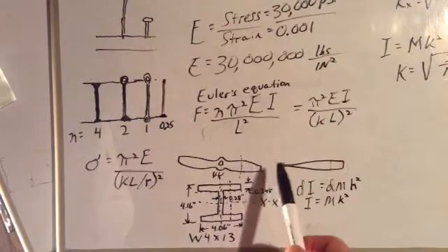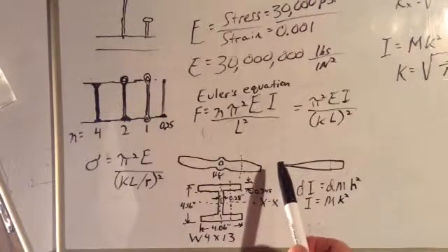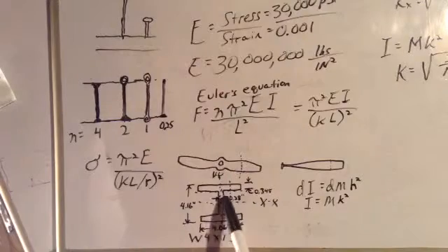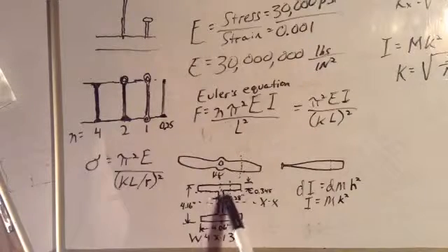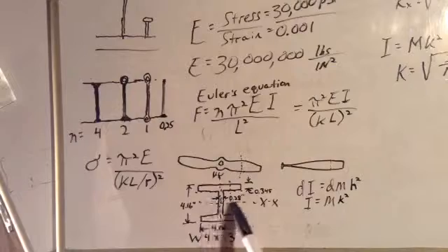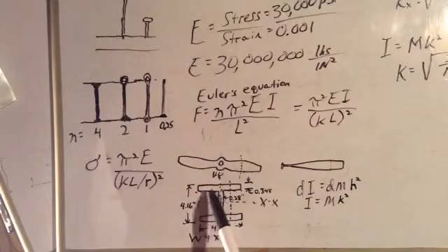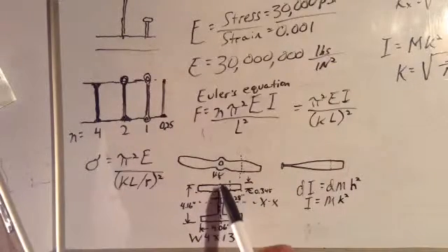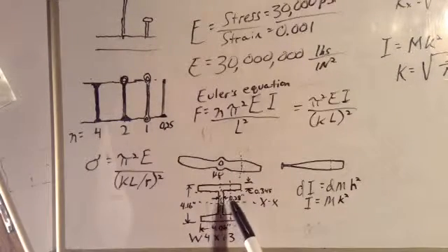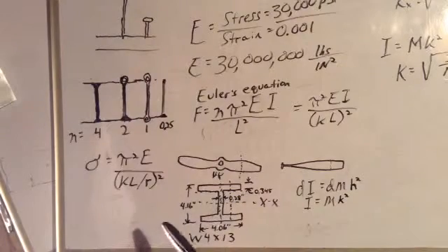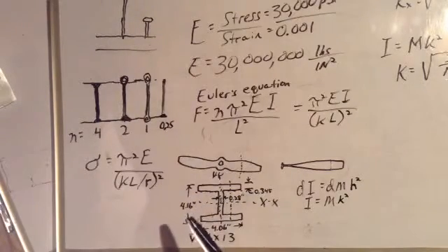Okay, while area moment of inertia is typically in units of meters to the fourth, because to find the area moment of inertia, we take all these little incremental units of area times the square of their distance from the axis. So area is already a distance squared, times another distance squared gives you a distance to the fourth. So area moment of inertia will typically be in meters to the fourth or inches to the fourth, whatever.